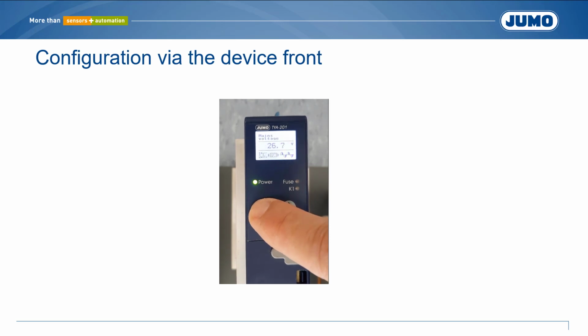After configuration, a setpoint for the power is specified in manual mode for functional testing. Load current and load voltage are displayed directly. Finally, the setpoint is specified by the temperature controller. All electrical variables are available at the power controller for diagnostics.